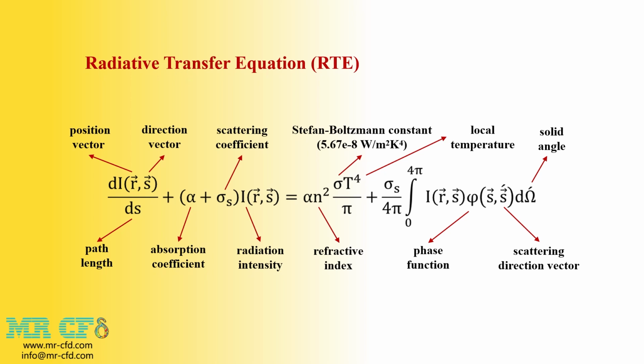When it comes to fluid behavior analysis, as usual, we have to go to the transport equation. At the time of defining the radiation model, the software must solve a general radiative transport equation, RTE, for the computational domain. This equation applies to all radiation methods, but according to the chosen method, this equation can be changed and some of its terms can be removed. Look at the equation in the picture. The parameters in the radiative transfer equation are introduced.